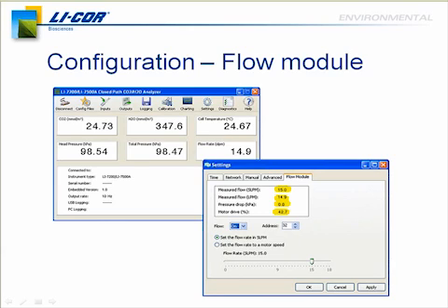And that was a really key driver for this product and this project, was how can we help people get maximum data collection at remote sites without needing power. And that's where this flow module comes into play. Again, it's very easy to interface with, and it provides 15 liters of flow, which is optimal for eddy covariance measurements with this analyzer. And it can provide those 15 liters of flow for 15 watts of power nominally.